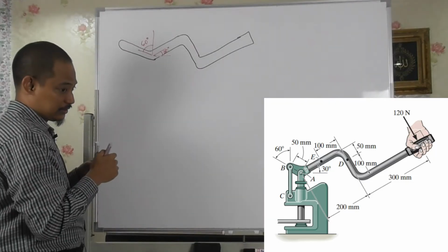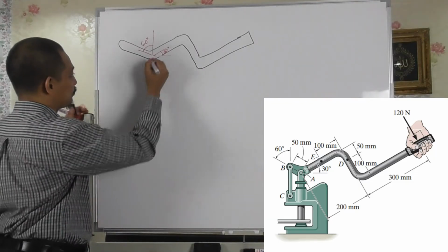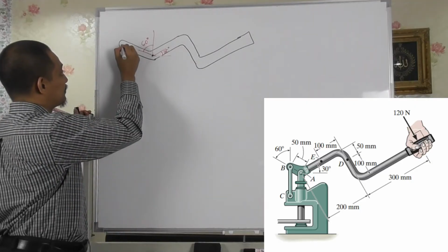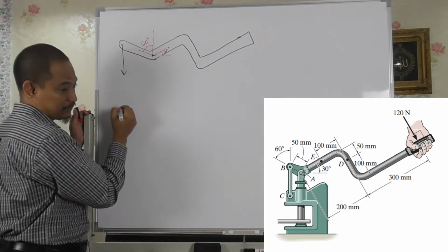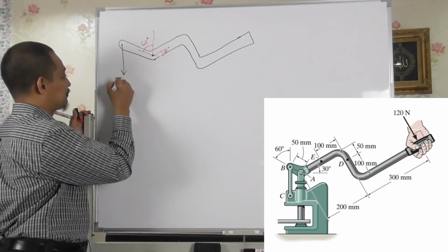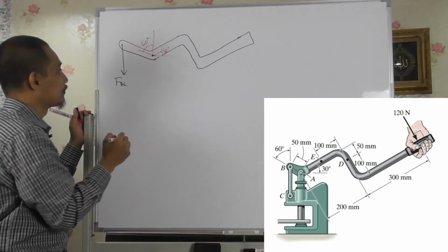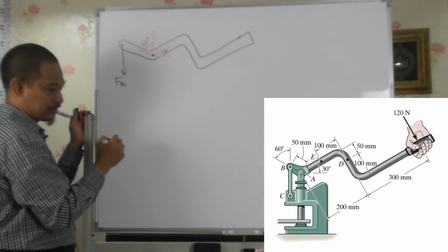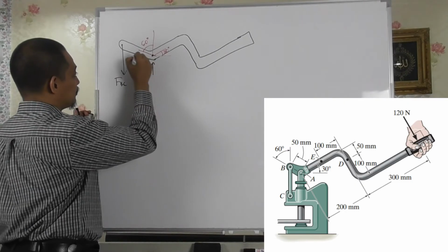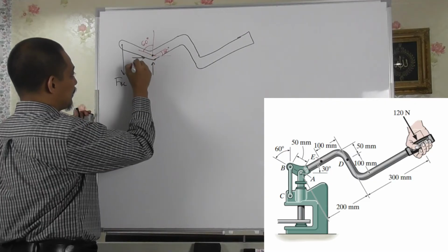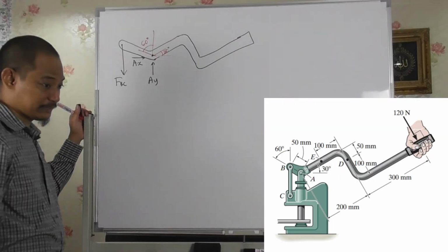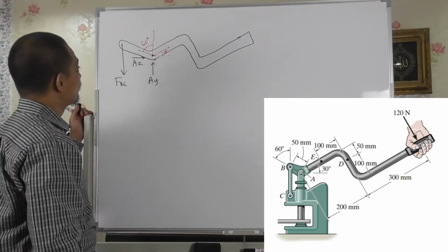Anyway, so we have 2 points here. One point A and point B, right? So for point BC, you can straight away assume that it's either tension or compression. So let's say FBC, and at point A, obviously that is a pin support, so you have, let's assume that way, right? So Ax, Ay, we assume the direction, the distance, right?